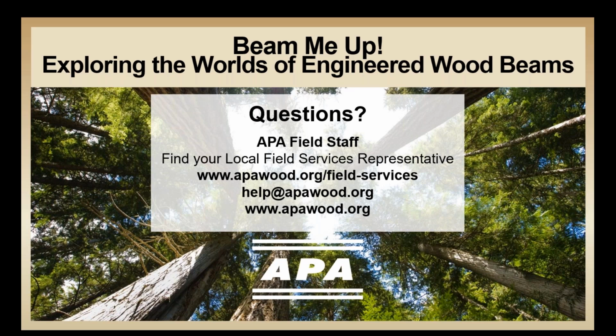Okay, so let me first answer by noting that you're not allowed to rip glulam to shallower depths. We'll just go with that because I think we understand how the plies are different on the ends of the member, so that's why you can't rip them, because of the different plies. But SCL, on the other hand, is a little different in that the material is consistent throughout the depth of the member. So cutting a deeper beam doesn't affect the reference design values, the raw values, the F sub B's. You should check with your manufacturer before you say you're cutting a 14-inch to a 9.5. They should really match the strength properties.